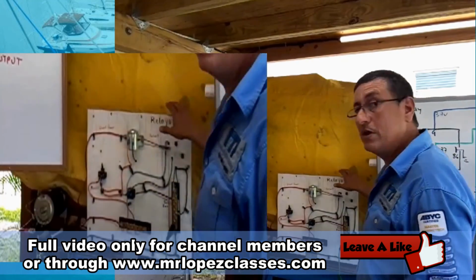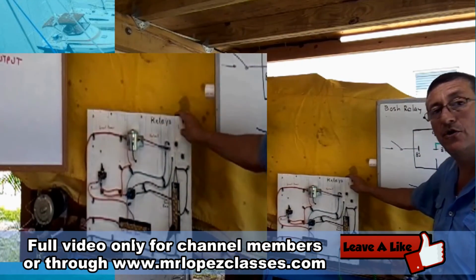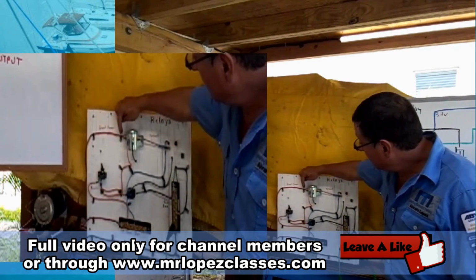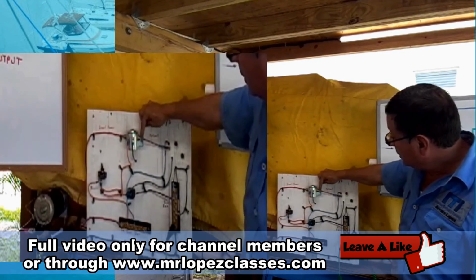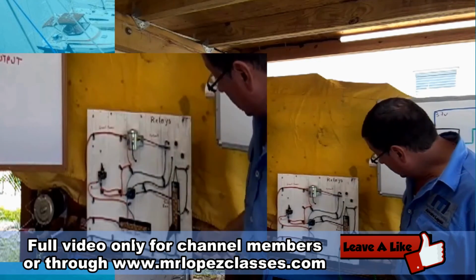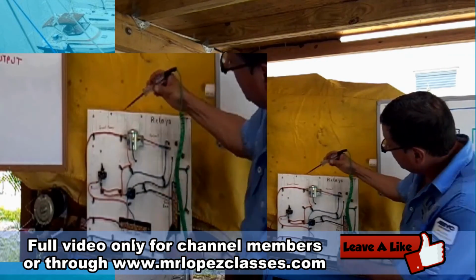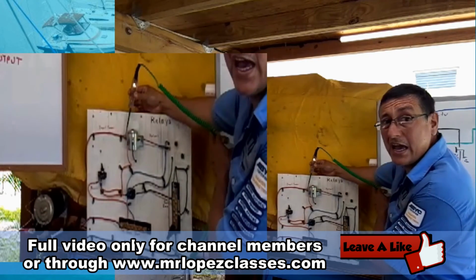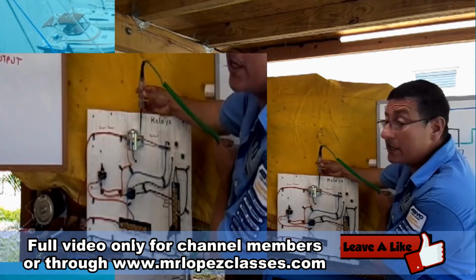I have a good example in this board that I prepared for you. I have the start relay. That's the input. This is the output. At this moment it is open. If I check with the probe, I have power here. I have power here. The light is on, but I don't have power here.